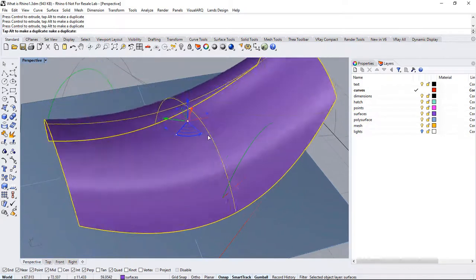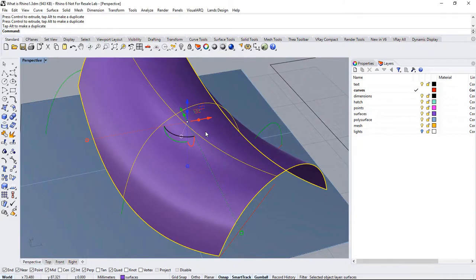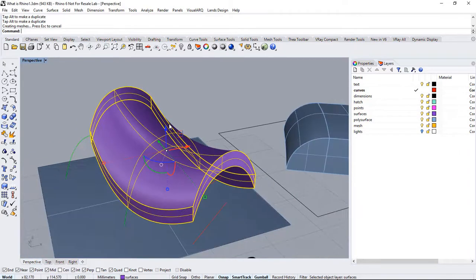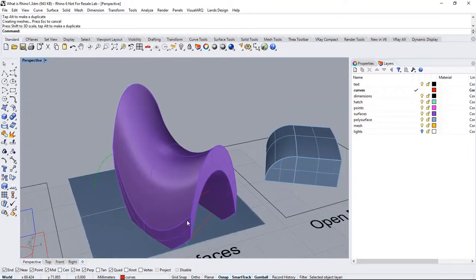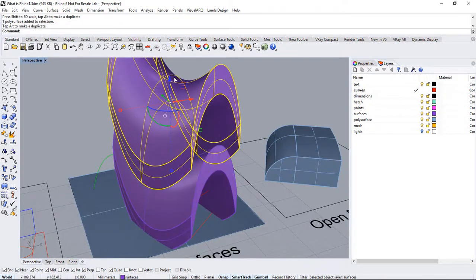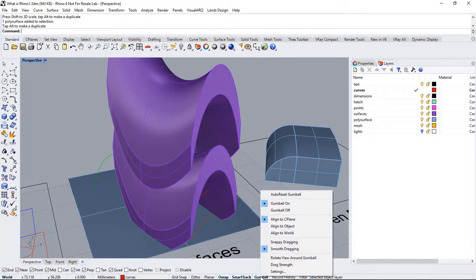We can do the same with the arcs, which allow us to rotate the object, or click inside to rotate it to a certain angle. If we click on the sphere, we can extrude the object, giving it a certain thickness. The squares allow us to scale the object in one direction. A small trick: try dragging an arrow while holding down the Alt key. You'll make a copy of the object. If you right-click on the Gumball down by the modeling aids, you'll be able to access and change the Gumball settings.